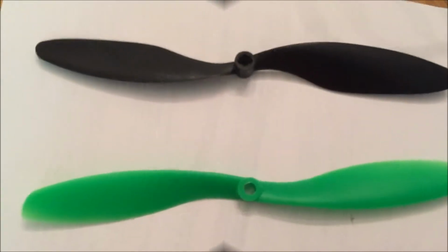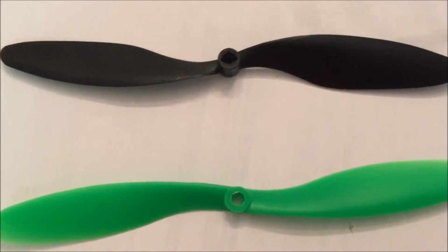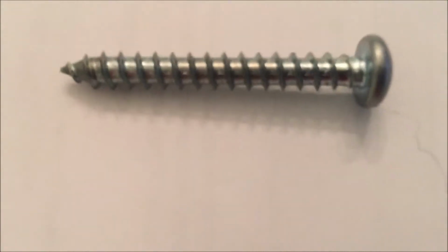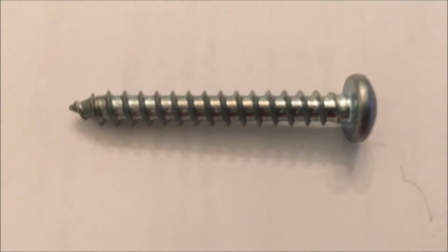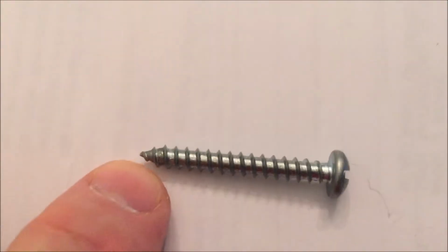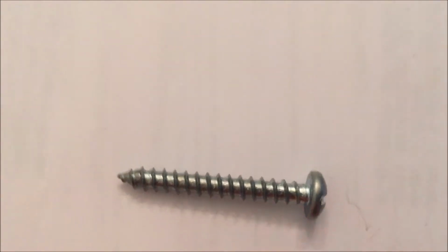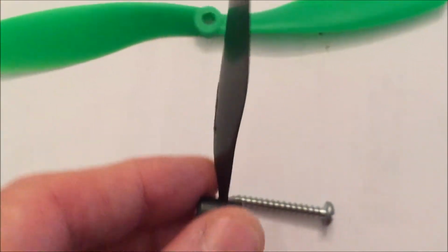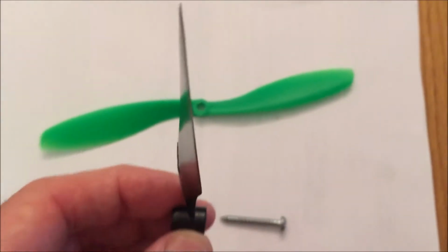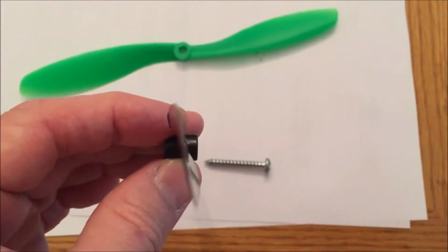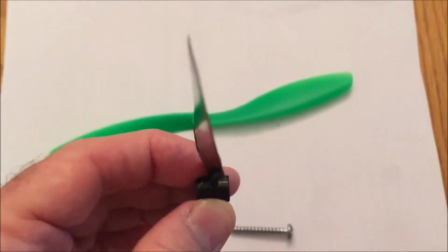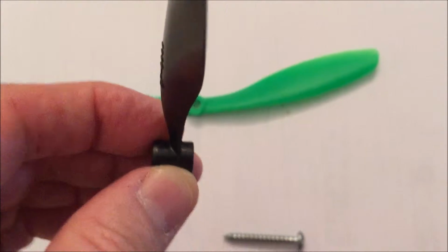Let's look at how to label these props as clockwise or counterclockwise. So let's do that in the context of the standard. Here is a clockwise right-hand threaded screw. So here we have the front of the screw, here we have the back of the screw. Let's look at the props in the same way. So we'll have the front of the prop facing the same direction as the screw. And if we do that and we look at the twist of the blades, we see that that angle is very similar to that of the screw. So this is a clockwise right-hand propeller.